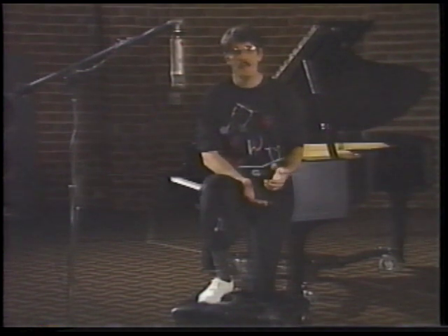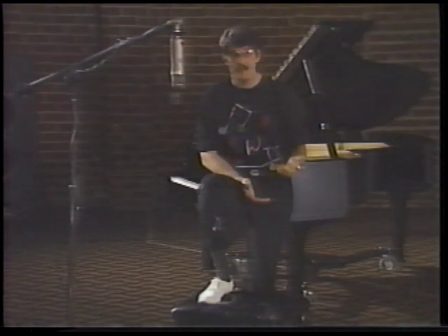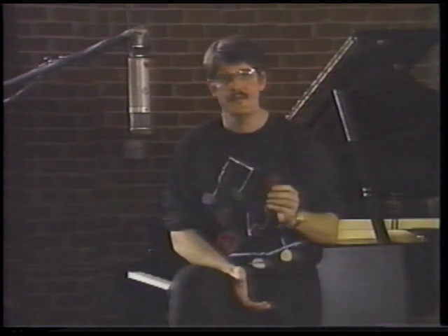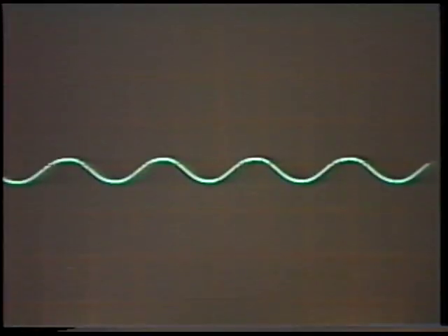A loud rock band will be between 100 and 125 dB SPL, and the studio that we're in is at about 10 dB SPL. Level meters are referenced to a certain level of signal into a specific resistance. The most common average operating levels are minus 10 dB or plus 4 dB. In correctly designed contemporary equipment, a minus 10 system will provide equal quality to a plus 4 system.